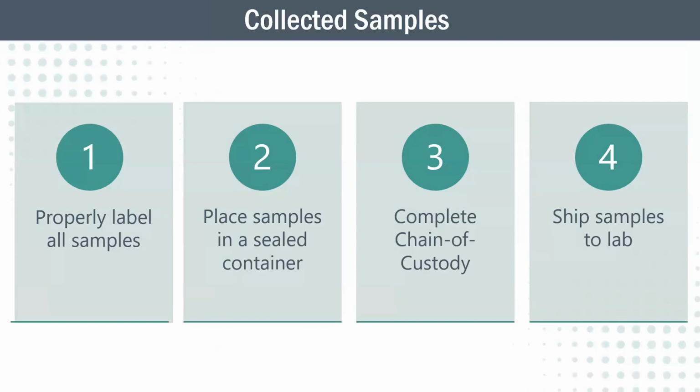Something I learned the hard way is that inside each one of those aerosol cassettes is a little glass slide. So you want to handle those carefully and pack them carefully when you ship them to the lab, because if they break, they cannot analyze them. Out of the dozens and dozens that I've pulled, I had one where FedEx had thrown the package down and I didn't have it wrapped in bubble wrap, and that little slide broke. So we weren't able to get a result on that one. It's just something to keep in mind, that there is a little glass slide inside those aerosols. Yeah, great point. Pack them good.